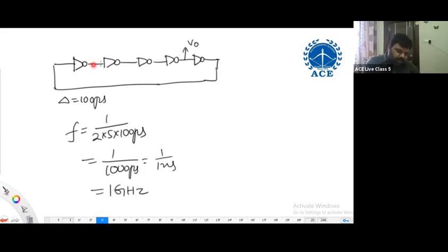When I'm using that output here, that means after 4 inverters, it is not becoming bistable. Right? In this ring circuit, how many inverters are there? Where I am taking output doesn't matter, because it is just a cycle, or repetition, right? So you can push this inverter this side, then obviously again we'll be getting the same circuit.